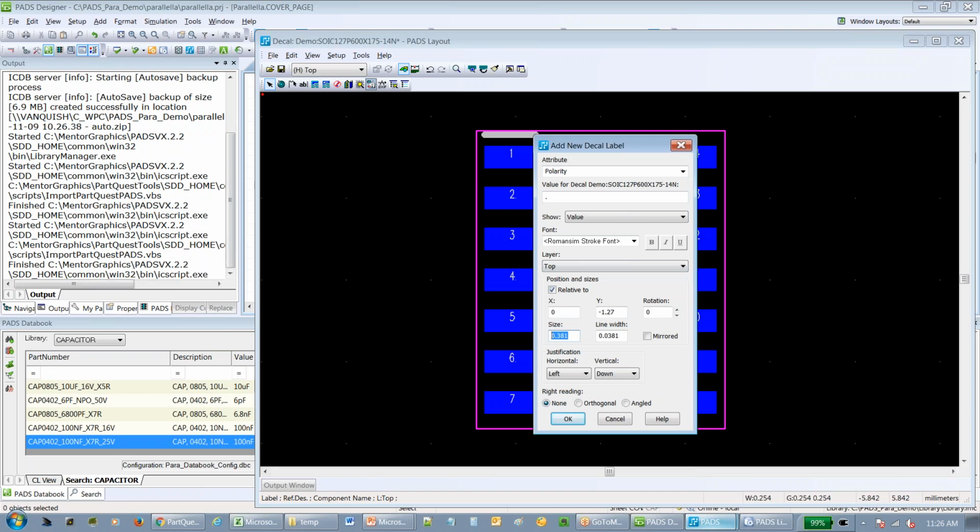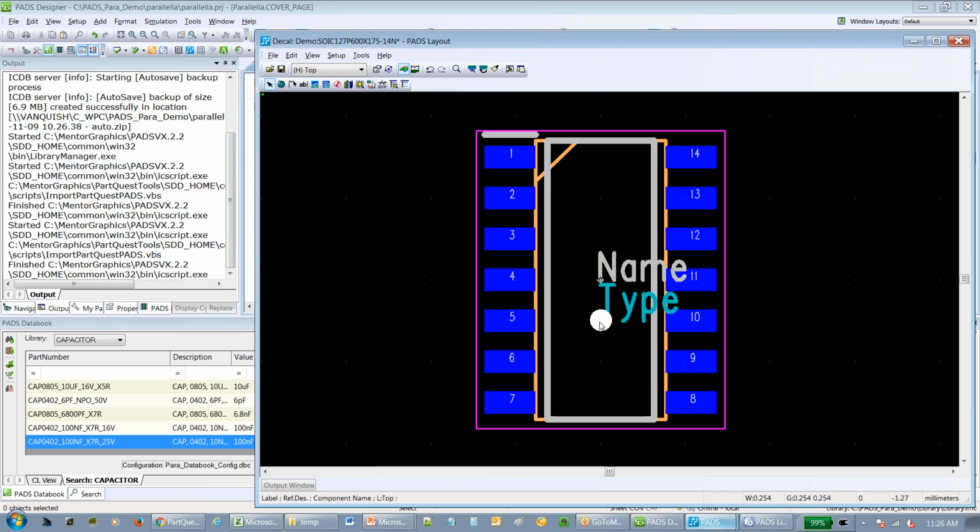But then you can control the size of it. So I'm going to make, since I want it to be a circle, I'm going to set the line width and the size the exact same. That may seem counterintuitive, but you'll see here in a second when I click OK, you'll see it ends up now as a nice circle, a big circle that I can move around.